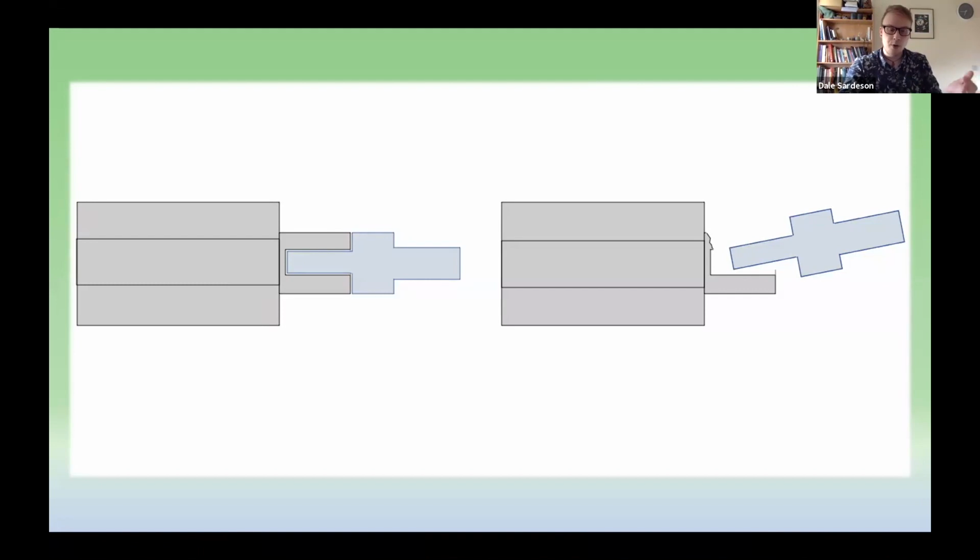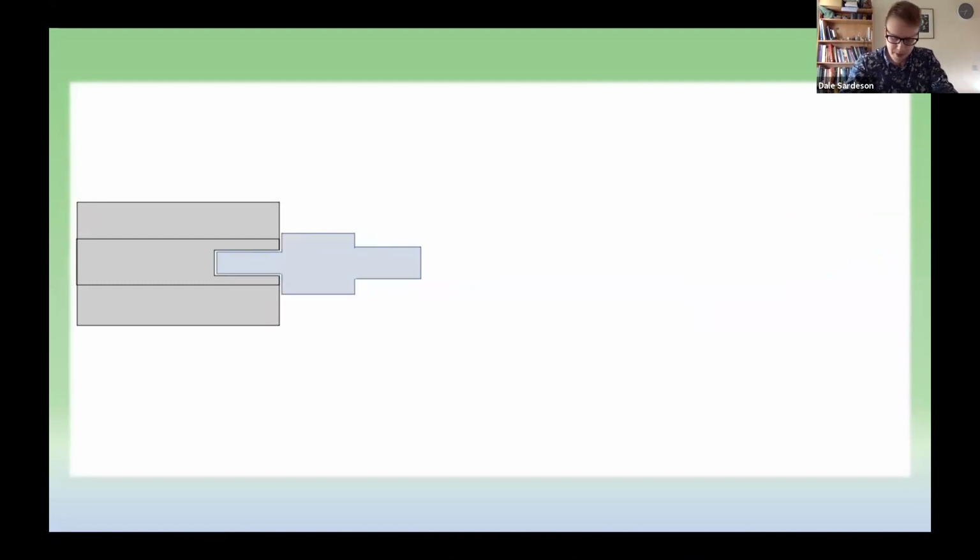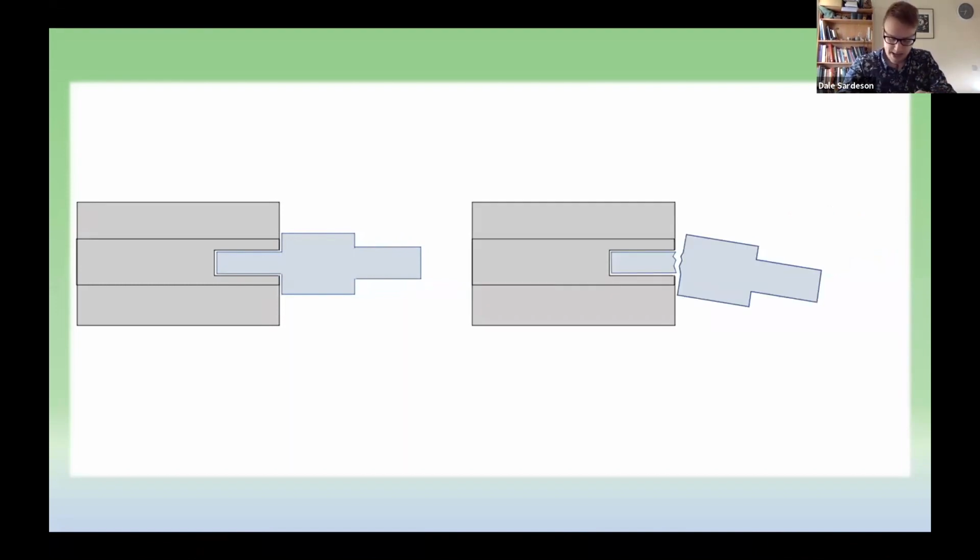So obviously I had to remove the broken part of the arbor and take it right back to close to the pinion and then fit a new extension, like this example here. I tested it for a few days and returned it to the client. Two weeks later, I got another phone call and it had failed again. And this time it was actually my new material that had fractured. A sharp angular step in a component like this is always going to be a potential weak point. And the powerful locking force was obviously too much for the small diameter of the extension shank to withstand.